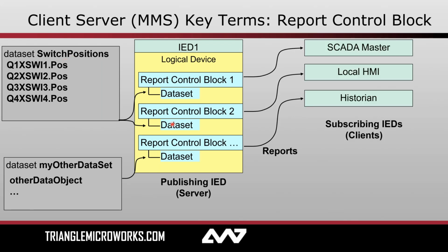And that's because this is not a multicast system like we'll be talking about in a moment. Each report control block, or at least each instance of a report control block, is associated with a single subscribing IED. So these subscribers or clients over here, to use 61850 terminology, might be a SCADA master, a local HMI, a historian, anyone that wants to consume that information from our different pieces of secondary equipment.